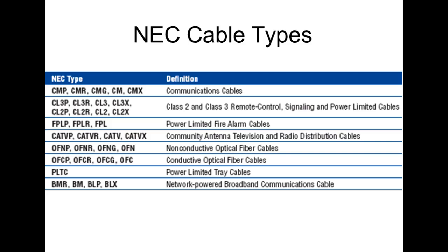If you're replacing a cable, if a cable gets cut or broke or something like that, they print this information on the jacket somewhere, and they do it every foot or so. So what you need to do is find that information on the cable, and you need to replace it with the same jacket grading that was originally put in there, or one that's better.